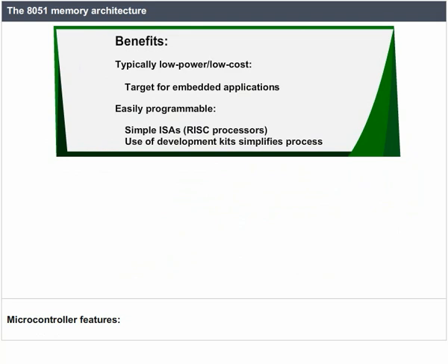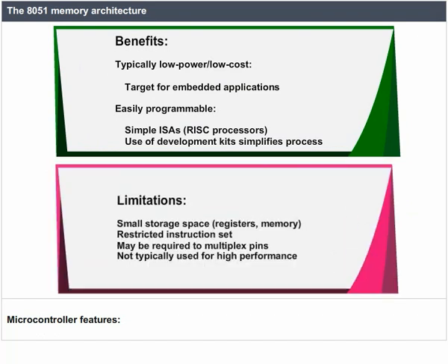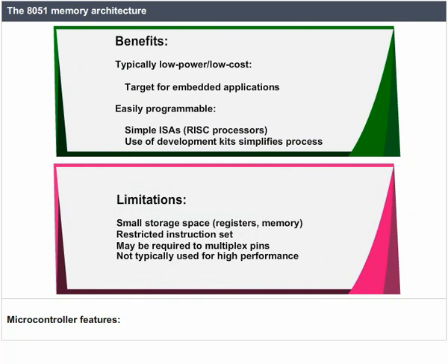Microcontroller features. Benefits. Typically low power or low cost. Target for embedded applications. Easily programmable. Simple ISAs, RISC processors. Use of development kits simplifies the process. Limitations. Small storage space, registers and memory. Restricted instruction set. May be required to multiplex pins. Not typically used for high performance.